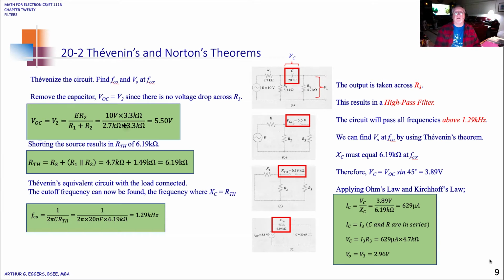This looks like a very busy slide here, but if we take a look at it step by step, it's a little easier. So the use of Thevenin's theorem can simplify the solutions to some AC circuits. For example, consider the circuit that we've got here at the top. Suppose we wanted to find the voltage drop across the capacitor. The problem, as we said before, would be fairly complex. So using Thevenin's theorem reduces the problem to a simple circuit and makes it quite easy to calculate.